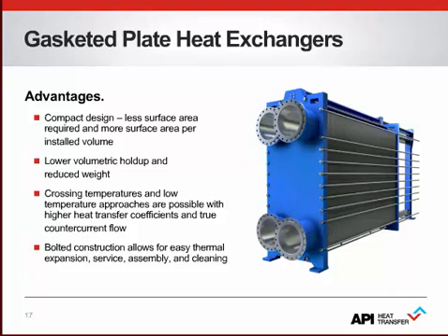Due to the high thermal efficiency, the plate heat exchanger is typically much smaller and lighter than a shell and tube heat exchanger. Furthermore, more surface area can be installed on a smaller footprint. Additionally, there is less space between the plates than between pipes. This is why the hold-up volume is also smaller. This is especially interesting if you have expensive or dangerous fluids.